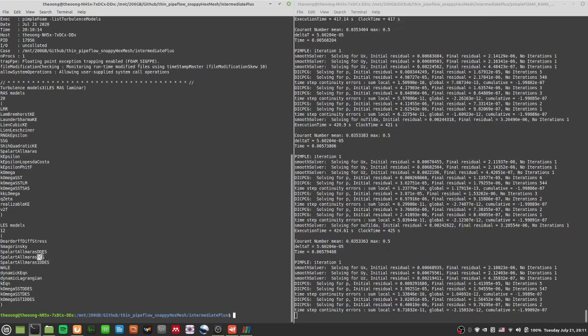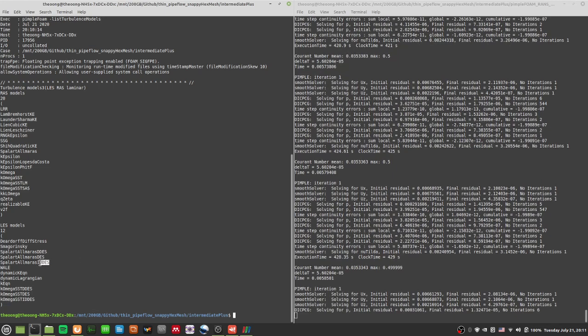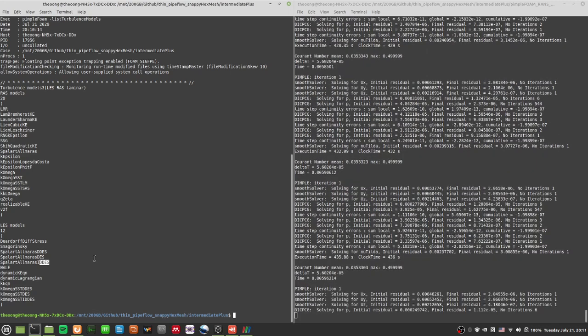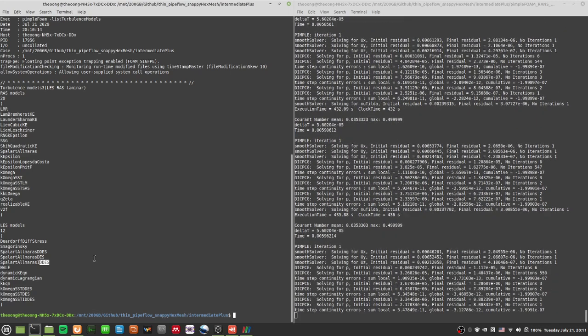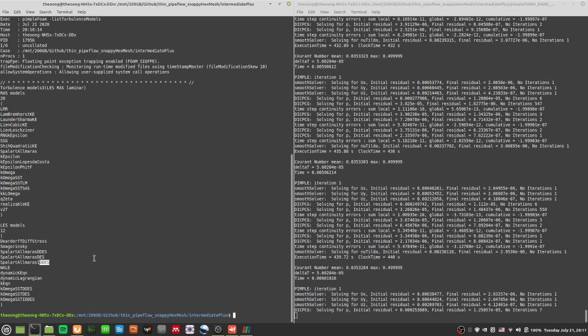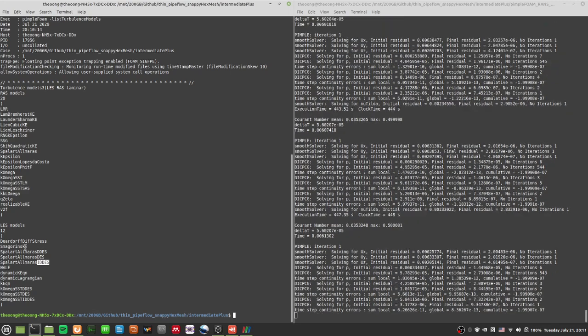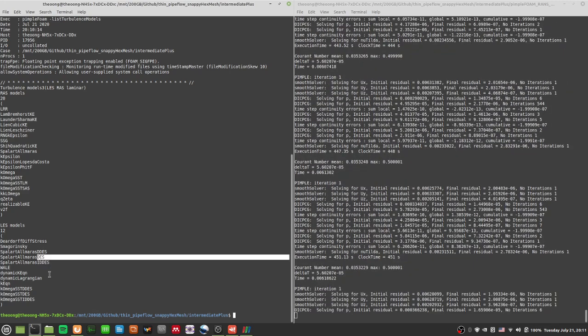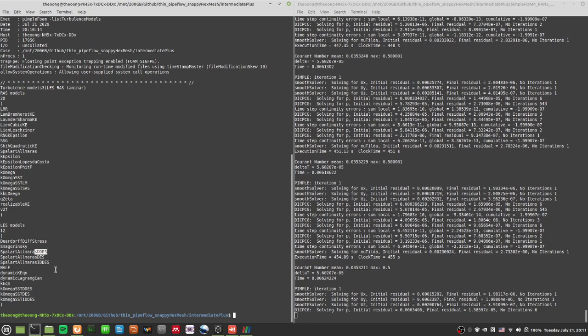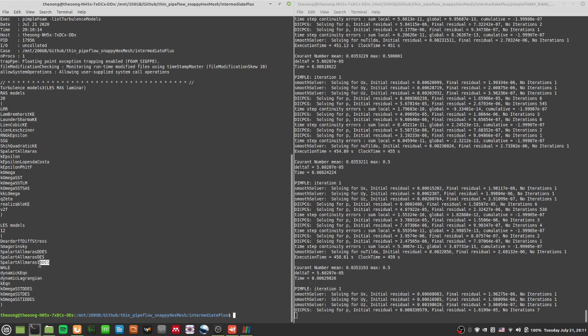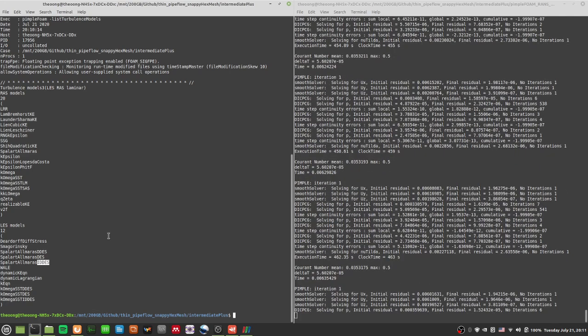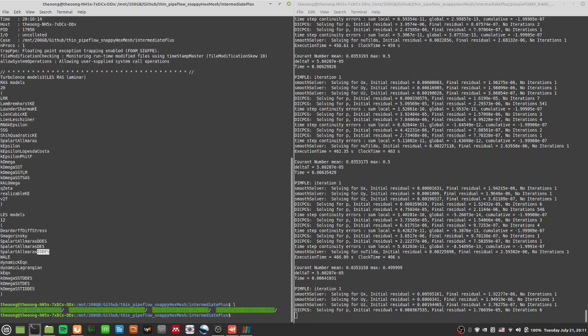And what is the difference between DES, DDES, and IDDES? You need to take a look at my turbulence modeling video series. You will be able to see what the differences are. I elaborate a lot on that. But if you are in doubt, just use the IDDES model. This is the latest model. DES is the first iteration of the hybrid. With DDES, they found out there were some problems, so they improved it. IDDES improves on that again to expand the functionality. So just use IDDES if you are really in doubt and not sure what to do.